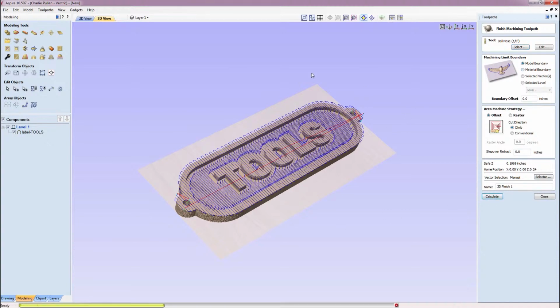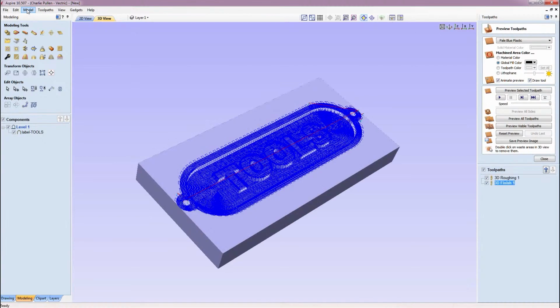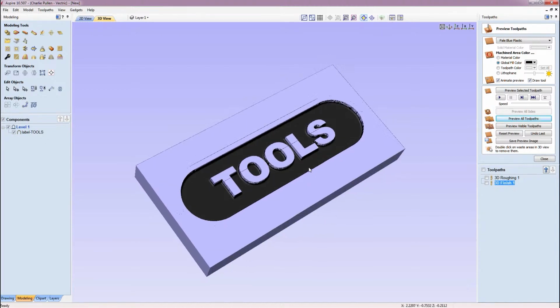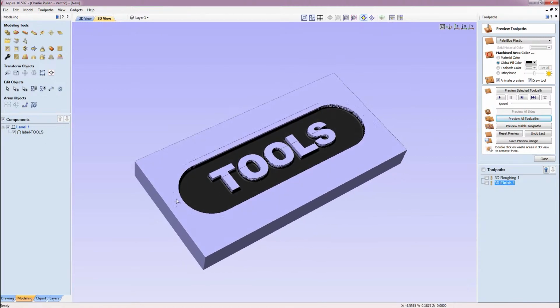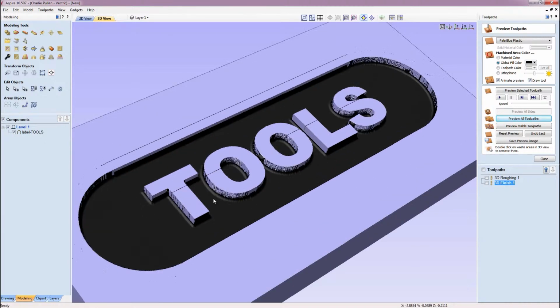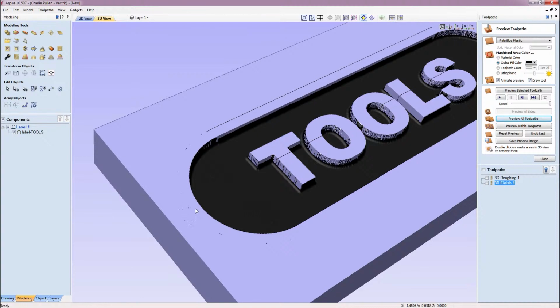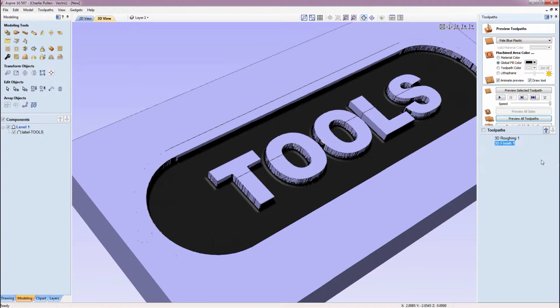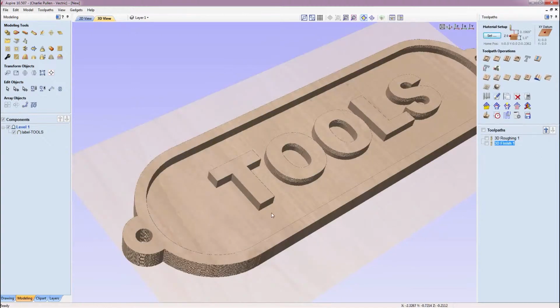And then this will just be a common 3D toolpath to show you what this looks like. I'll quickly run it through on the preview at a low resolution so that we can see that in action. So let's put that down to standard. All of these toolpaths together will produce something a little bit like this. You can see there's some elements which don't translate well to a 3D toolpath and then don't get cut because of it, and there's not really much we can do about that, unfortunately. And overall, this toolpath is going to take quite a long time to actually process.